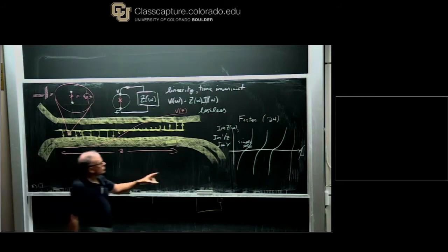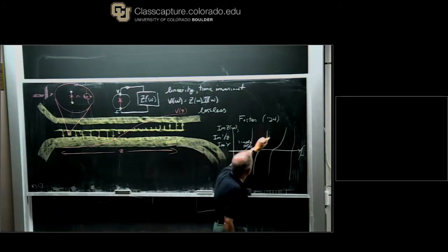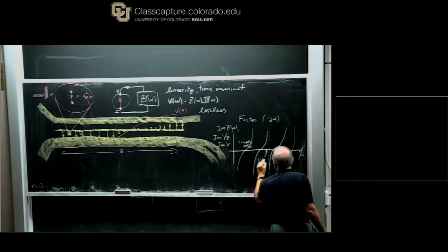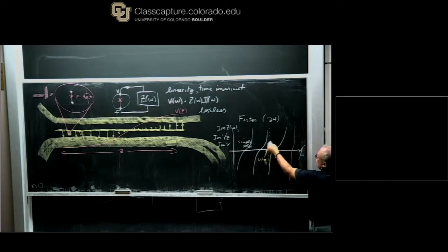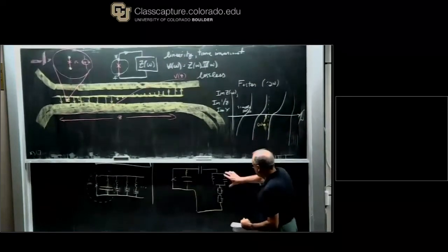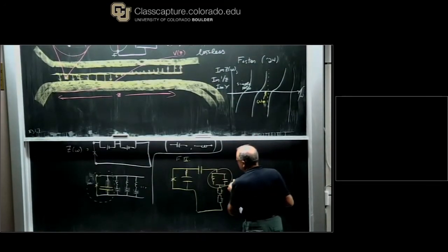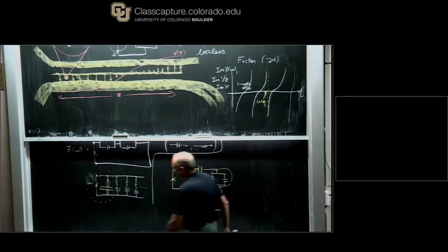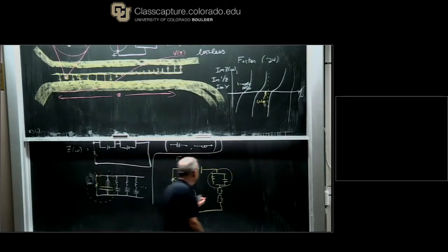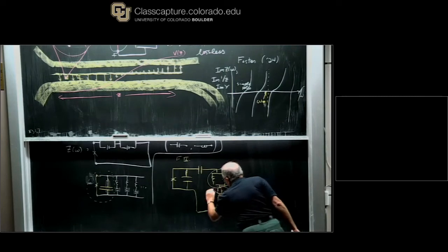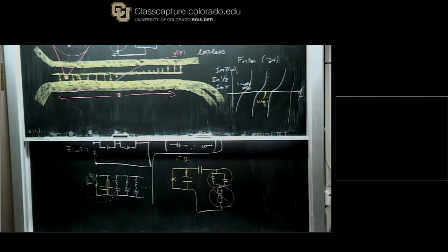But that's chosen by saying you have a pole here somewhere, and by design you make sure that the qubit frequency, omega q, in the sense of omega 0,1 of the transmon, is pretty close to one of these poles and not so close to others. So that will determine which of these LC sections you will choose to retain. And so the useful first approximation is just to get rid of the rest of these. But you don't have to.